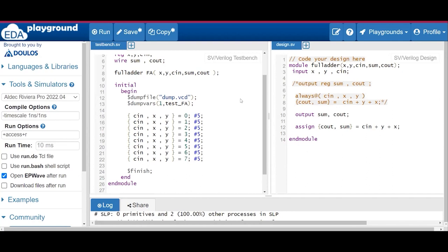Is it correct? Yes. A combinational logic circuit doesn't have any registers, right? That is just coding style where we use an always block. If you use an always block for combinational logic, it may generate some internal register, but it is not necessary. Okay, so it all depends on our coding style. Yes.